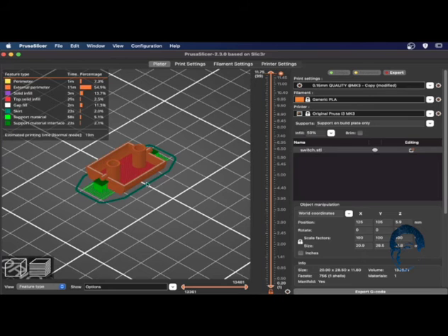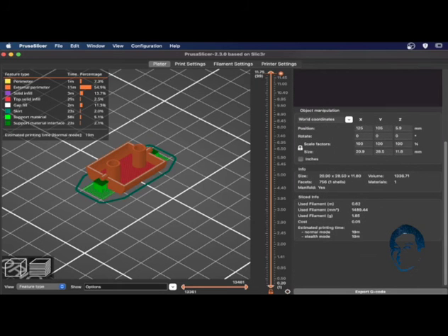By the way, if you notice here, there are some green color support structure being printed because this is created for the protruding part here, which is the pivot point. And for this one to be printed, the support here, I previously selected support on build plate only. So this is something you need to select if you have not selected that in order to get this support structure here.